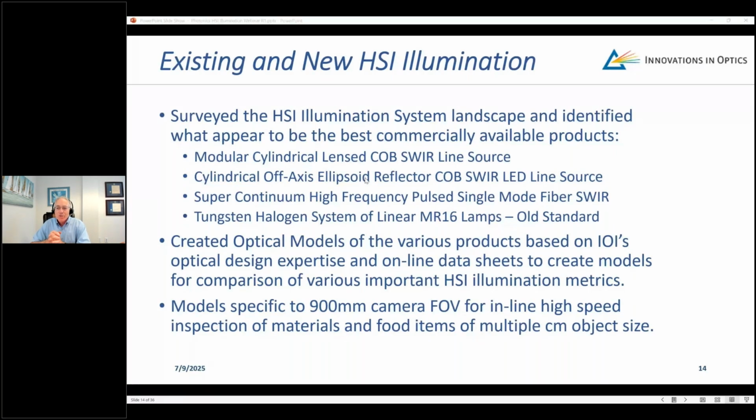And then we also wanted to look at another technology, the supercontinuum pulsed laser, which uses nonlinear effects at very high intensities at very short pulses to broaden the spectrum, which covers the range of 400 to about 2400 nanometers. Very interesting technology, but also extremely expensive. So in a cost-sensitive market, that won't work in all cases, or maybe few cases.